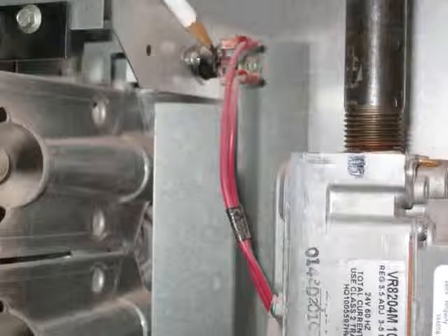If your unit is locked out, you should shut down the power to the unit, make sure the thermostat is not calling for either heat or cool, and turn it back on. You should also try to reset any manual switches. Some switches have a manual reset, a little red button on the back of the switch.